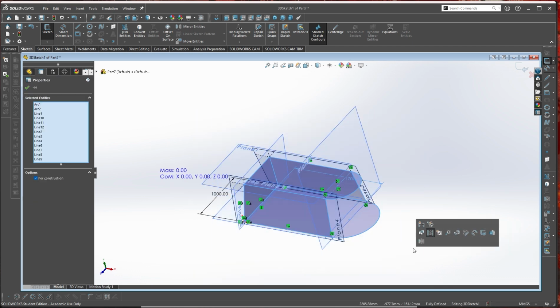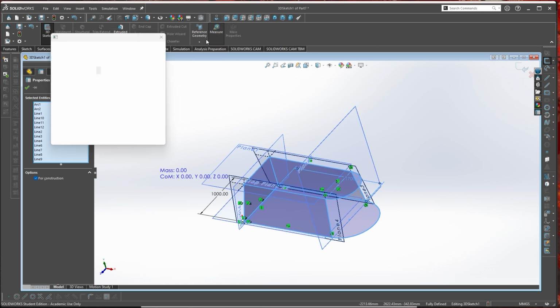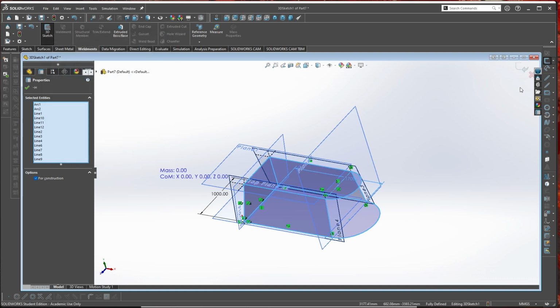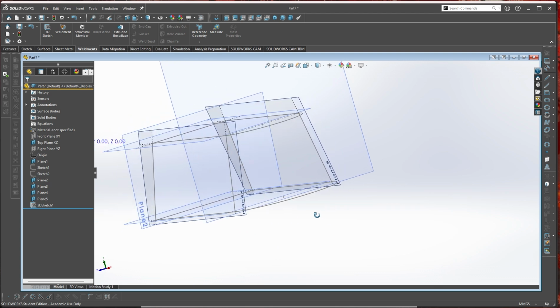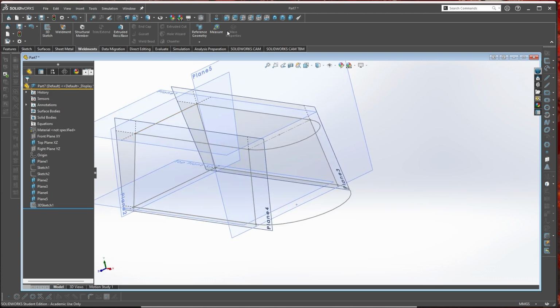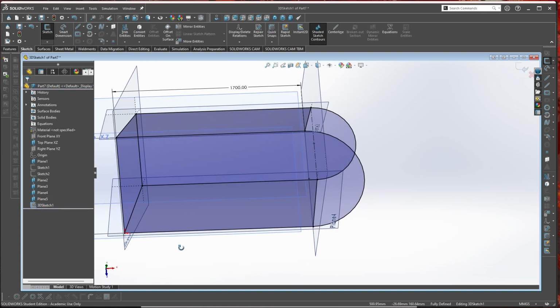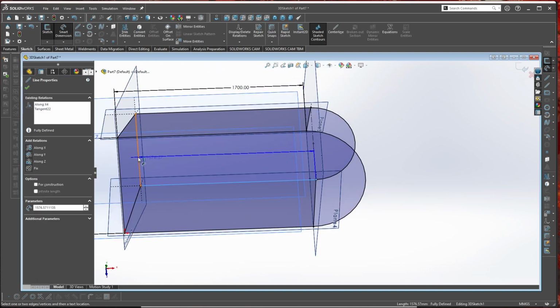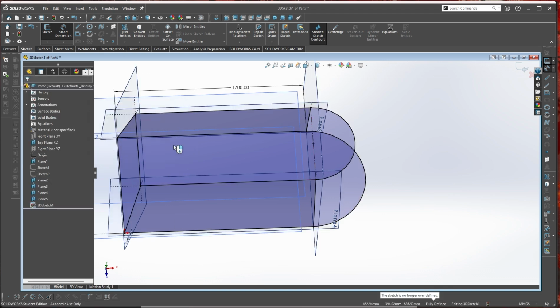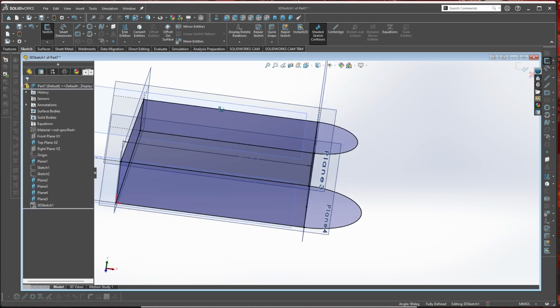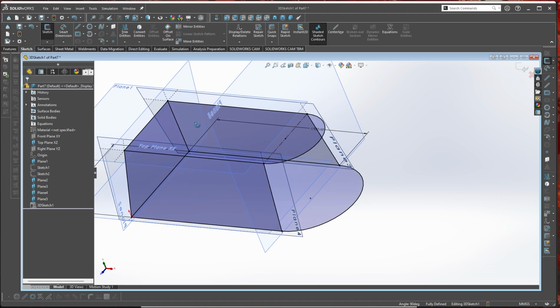Let's see if this works. Sometimes if you do everything that's really sketchy, you can do this all in one go. Oh, I got something else in there. So we're going to exit the sketch, look at these line entities, and let's measure again. Actually, before we do that, let's measure this angle right here. Right there. 90 degrees. Overdefined, but we are in good shape. Measure this, 90 degrees. So you can see everything now is in good shape. And that was the issue.